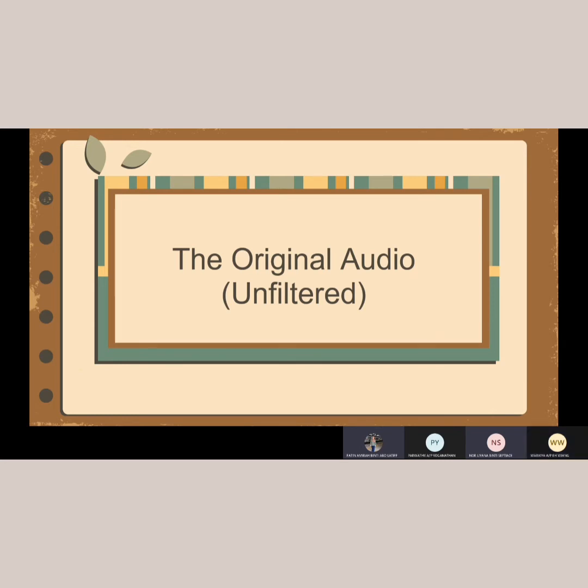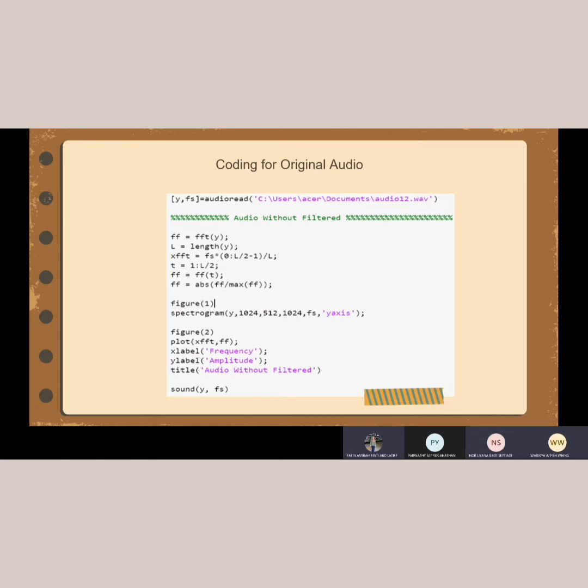Okay, in this part, I will explain the result that we obtained for the original unfiltered audio. This is the coding for the original audio. We are using the FFT function to see the frequency spectrum, and we use the spectrogram function to identify the signal in a visual way. From the coding, we also use the sound function to hear our audio signal. For the original audio, we recognize that the sound is noisy and loud.